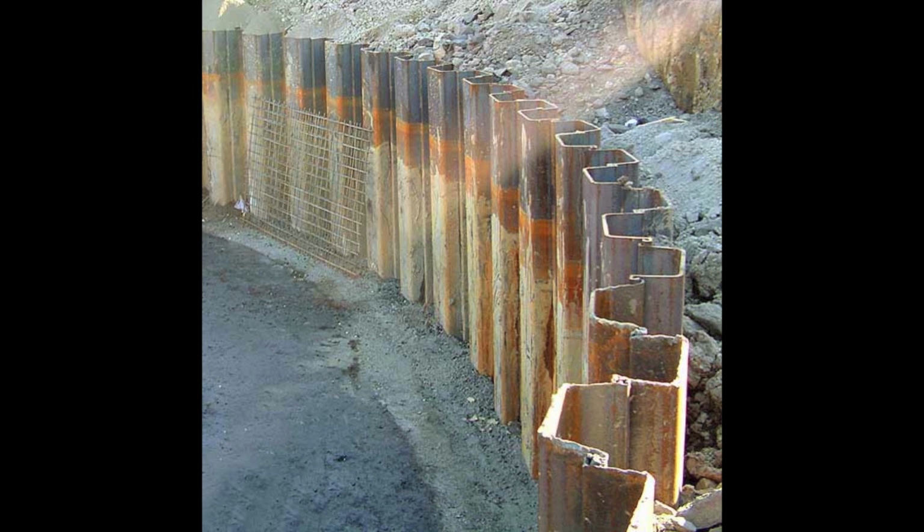The direct shear test is an experiment that involves finding the horizontal stress a soil can handle before failure. Imagine a retaining wall. The wall and soil must be capable of fighting horizontal stresses, or else the wall could crack, slide, or overturn. Failure in this case is defined as when the specimen reaches its maximum stress and can no longer sustain that stress level.